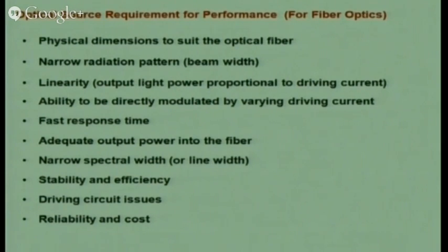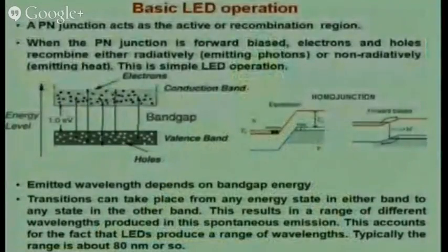Adequate power output is needed, so that I am in a position to couple the light to the fiber. Narrow spectral width is needed, meaning the bandwidth of the wavelengths should be narrow, because dispersion effects will come into play. Then stability and efficiency, driving circuit issues, reliability and cost. All these parameters one must consider while selecting these sources, which can be a laser source or an LED source.